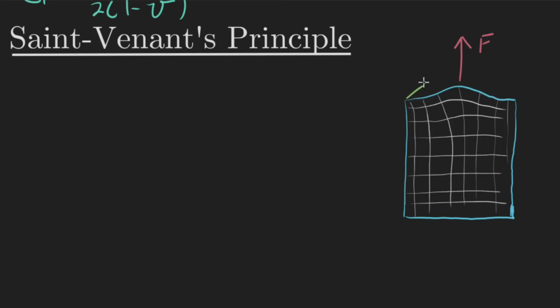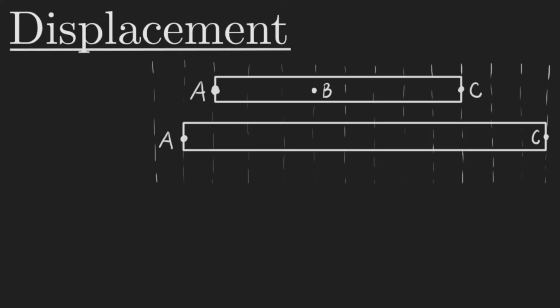More technically, what we would say is that the longest dimension in the lateral, so if we imagine we had some thickness here, whichever is higher, either the thickness or the width, which would be the width in this case, if we take the width and go that far away from where the load is applied, probably right around here, any localized effects from the force should basically disappear. And so this is the main idea with strain: we're assuming it's just averaging out. The localized effects of where we happen to apply it aren't actually going to affect the outcome on average, like the average strain.